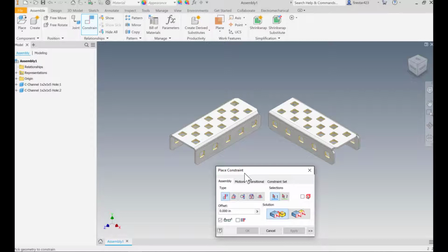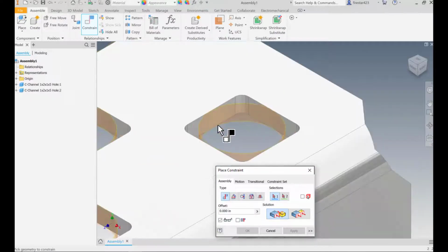An axis constraint forces two axes to become aligned. Finding it is a little bit more difficult than either of them because on our traditional menu right here, we can actually not find the axis constraint. Instead, we must choose an axis.